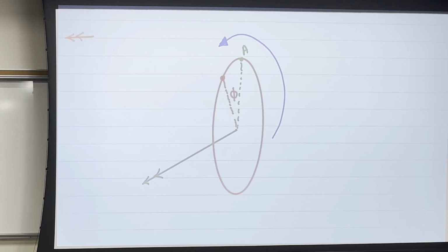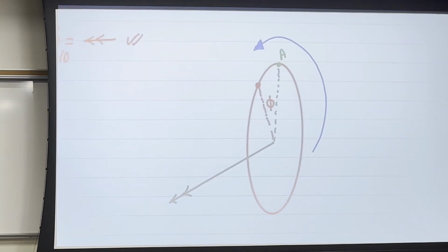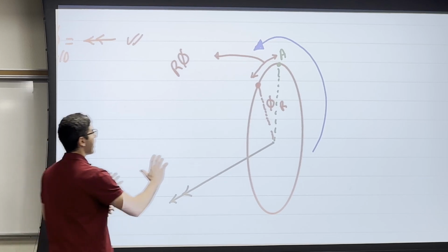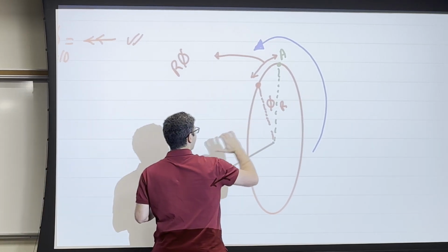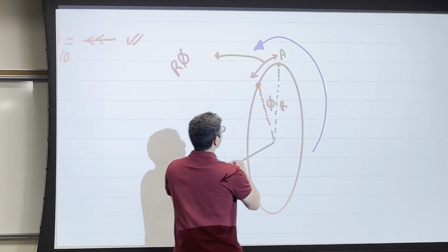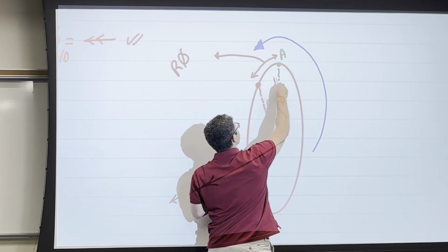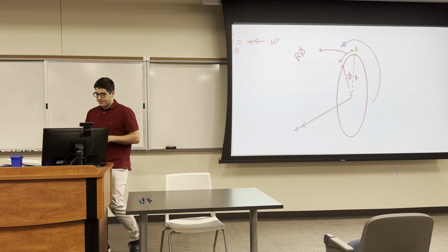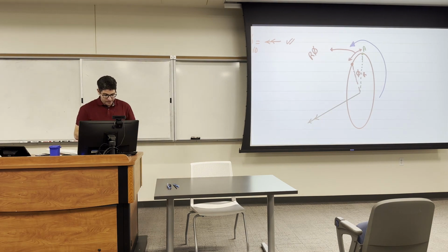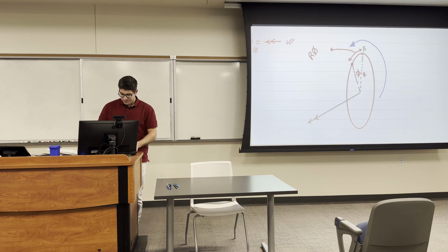and by an angle of twist, which you already solved, and you already have a radius, can you now find me this deformation? Yeah, you will simply say this is an arc length. You will say r times theta. So that's when we will, if we ended up with the angle of twist, phi, pointing outwards. And if we have it pointing inwards, instead of having displacement going this way, I'm gonna have a displacement going the other way. Okay? And that's all for this lecture, and I'll see you guys tomorrow. Thank you.